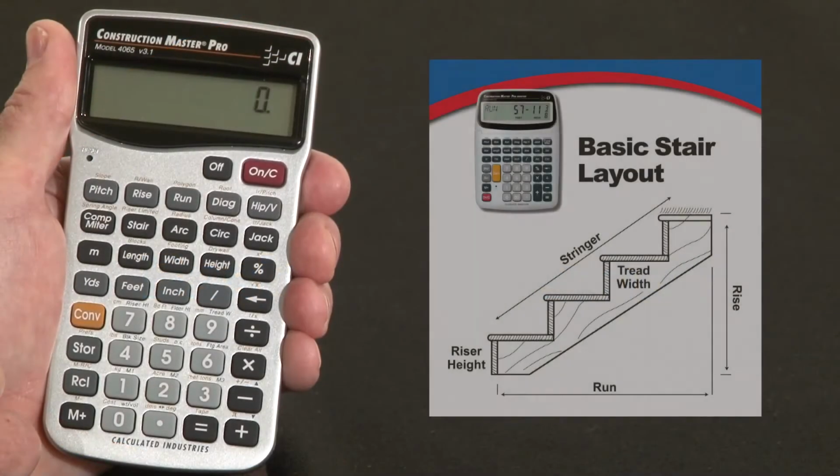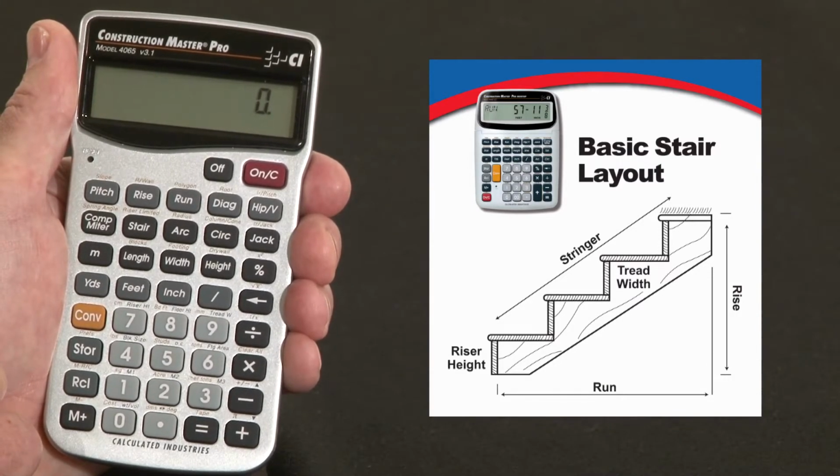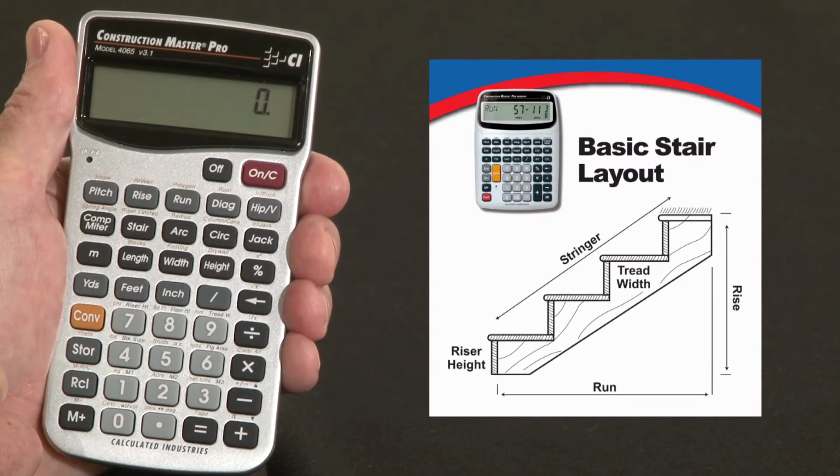Now let me show you how to calculate basic stair layouts using the Construction Master Pro. And keep in mind that the keystrokes will be exactly the same if you're using our trig model or our desktop model. This stair function can save hours of frustrating calculations and stair table lookups.